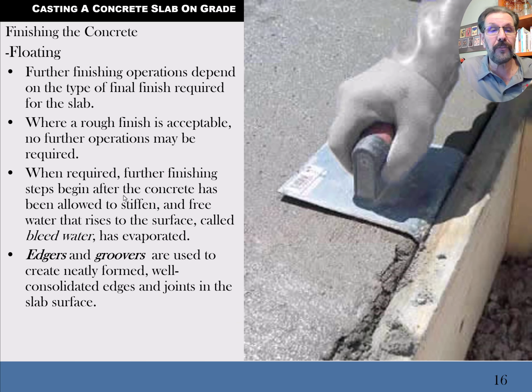And then you also do some float edging first, and I should find some pictures of actual floating tools. They're not going to be made of sheet metal, of stainless steel like you see here. The true floating edger will be made of bronze or magnesium, again, a coarser material that you're just roughing in the edge to push the gravel pieces in. But the whole goal is to move some of the chunky rocks in deeper, away from that rounded edge that you're trying to make, if you're trying to make a rounded edge.